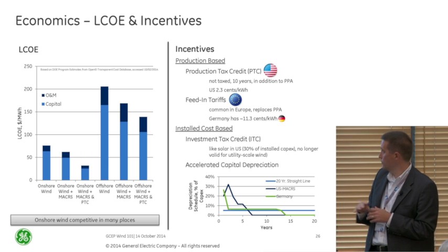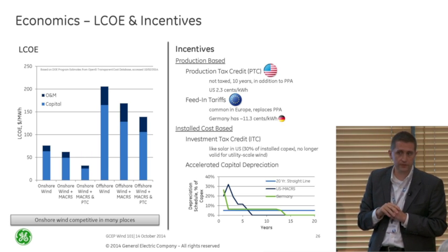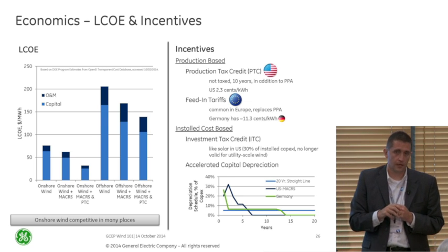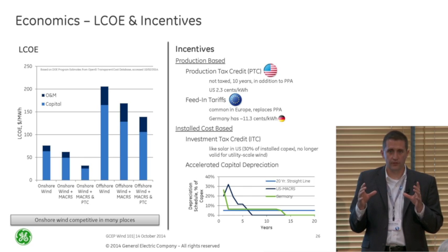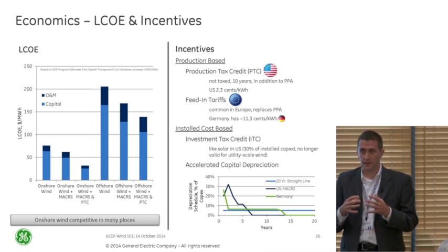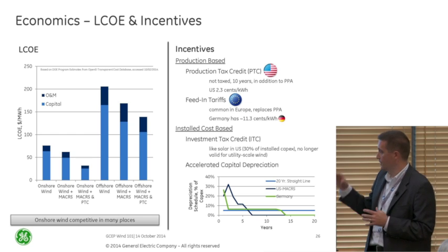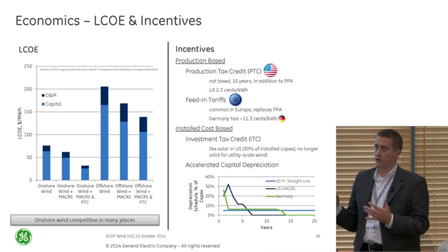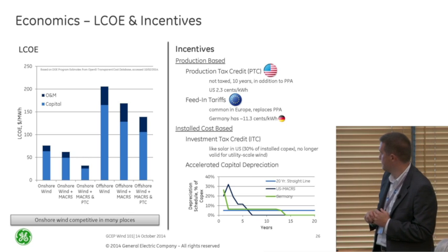Here's some looks of what the cost of offshore is in terms of LCOE. So you can see the big gap that you're seeing between these. Again, the big problem is, yeah, you've got a little bit better wind resource, but now you've had a lot of extra added cost in terms of the foundation. Often the foundation costs as much as the turbine. So that's how expensive these foundations are, especially if you get into about 20 meters of water depth. The foundation can become as much as the turbine, and you have to transmit all that electricity to land, and maybe you're 10 kilometers from shore. So that becomes a big added cost and shoots that way up.